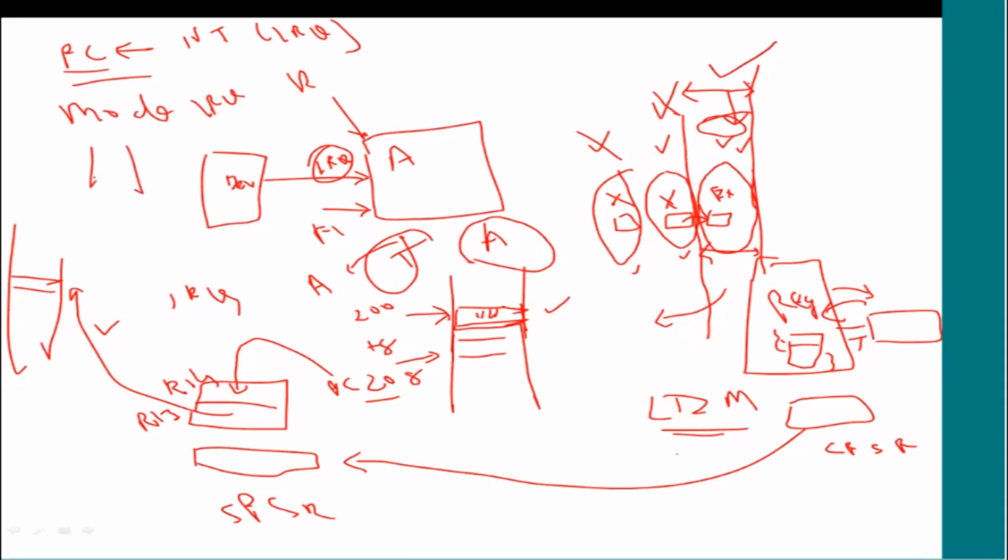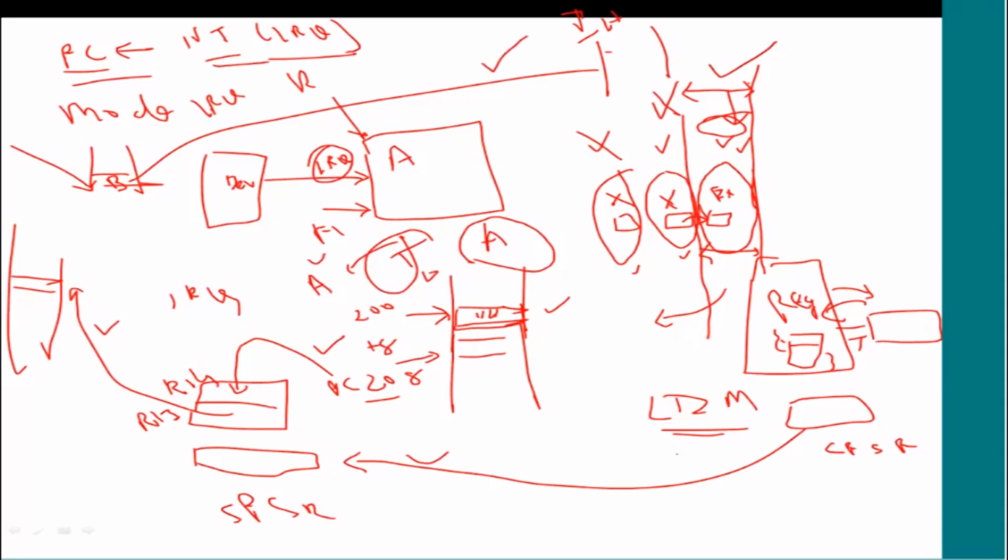For IRQ, it will be a branch there, so it will branch to the interrupt handler, and then the interrupt handler comes. So this much of the job is done. This is the first one, and this is also done together, and changing from Thumb mode to ARM mode is done here. Then it goes to the interrupt vector table, and then to the interrupt handler, and starts executing the handler.